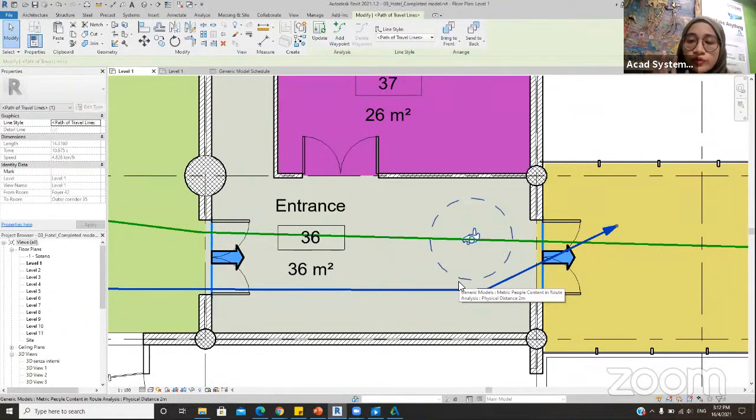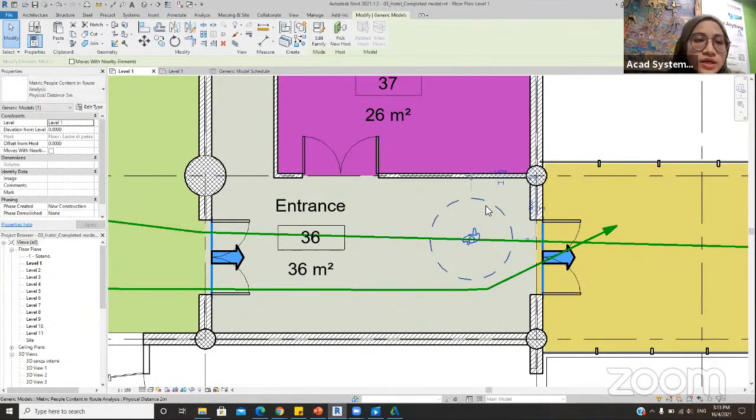So this is also essential if you want to put furniture, and for the safety of the people, you can also put this bubble of the blocker for them, so that when people go to that path, they will have some sense of security, although there is a furniture blocking the path. So I'll show you how that is working. If you go to edit here, edit family.